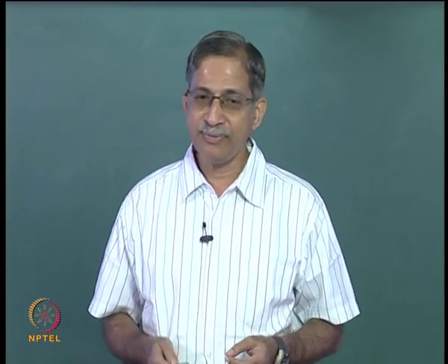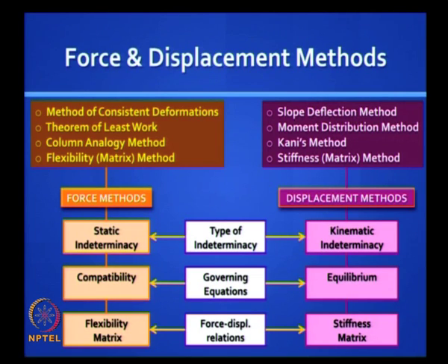Secondly, to solve the indeterminacy, you need to apply some equations, which are called governing equations. As you know very well, in force methods they are of the nature of compatibility equations, while in displacement methods they will be of the nature of equilibrium equations. And you need to express the displacements in terms of forces.